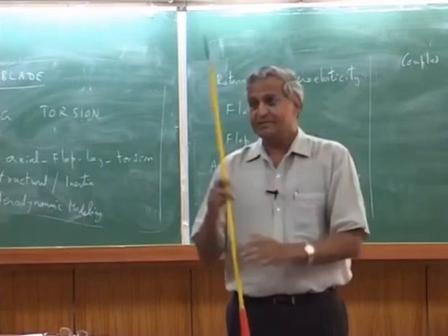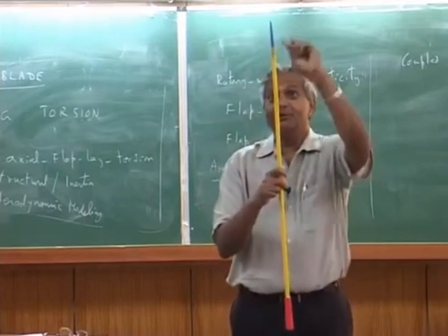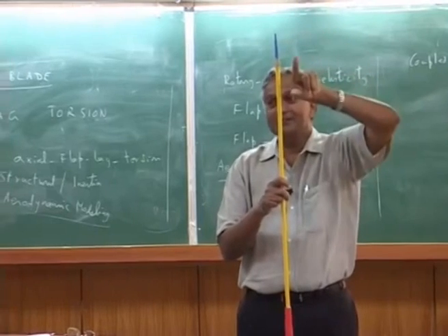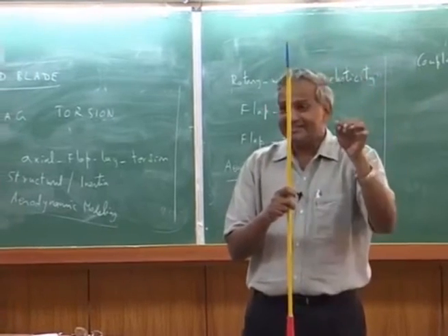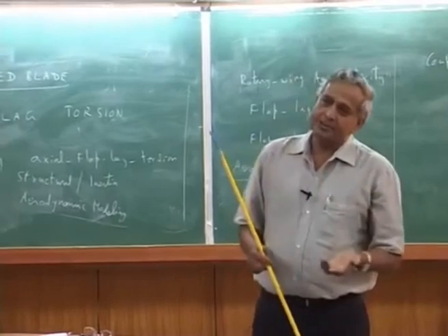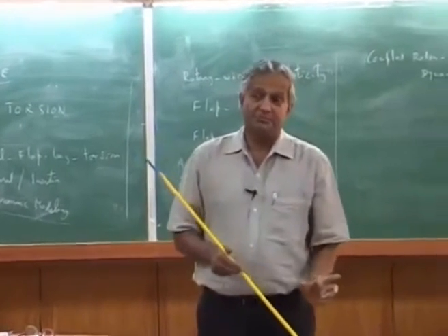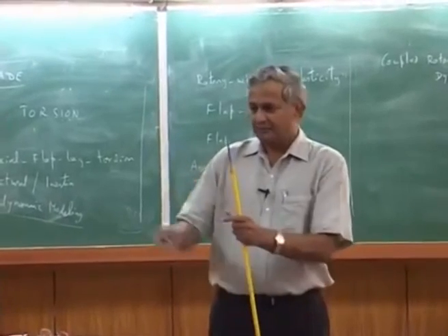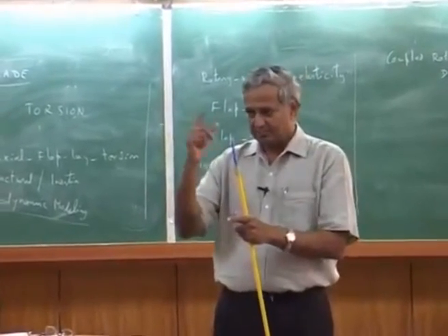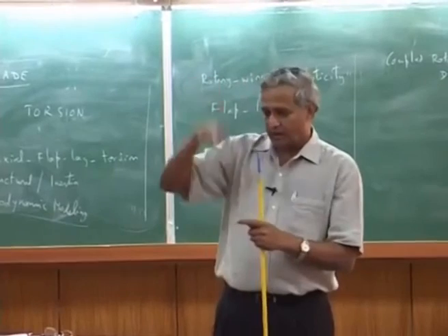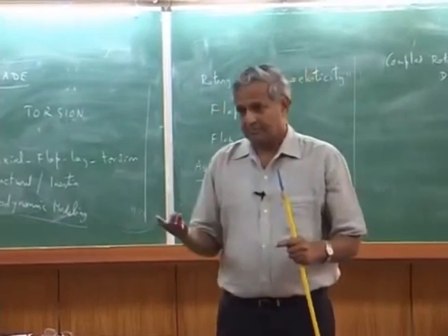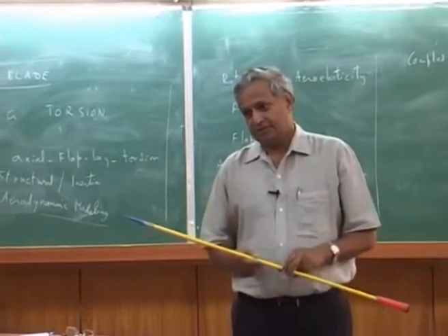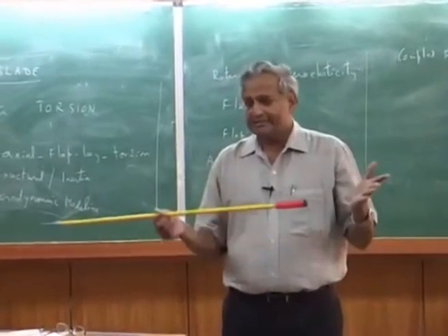Earlier they put some chalk and then brought a cloth. They will know where each color chalk hits. Then they will know this blade is high, that blade is low, then they change it. Another way is they also have vibration measurement. Because if blades are not tracking the same position, you will have a 1 per rev vibration. They will try to minimize that. Okay, and that is the way.